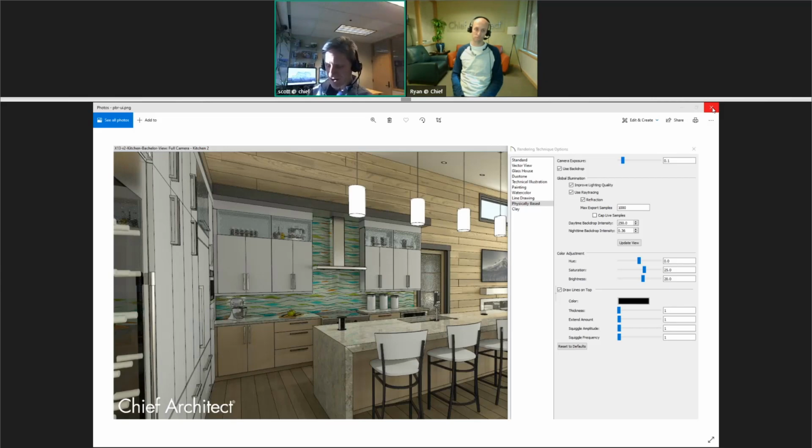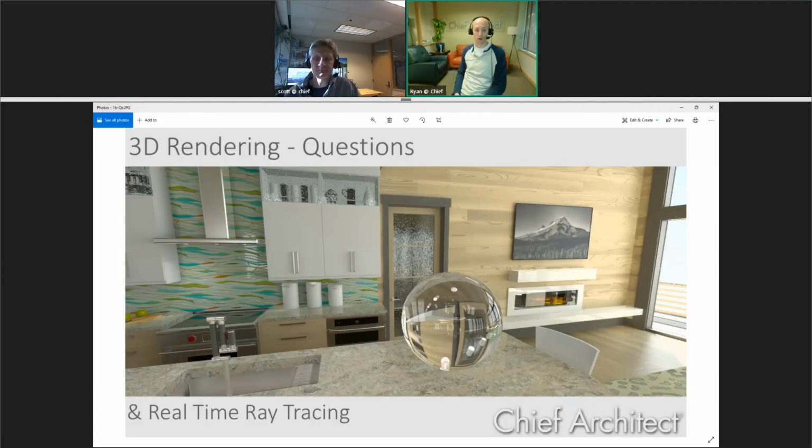Yeah. Hey, thanks for your question, Christopher. I'm going to ask Ryan to address the walkthrough question that you have. As far as recording walkthroughs, the amount of time that it takes to record a walkthrough is largely a function of how fast you can render a single frame in the program. So that's directly a function of how powerful your video card is. So it is very likely that if you switch to a more powerful video card, which the 3080 is, you will, in some cases, drastically reduce the amount of time it takes to record a walkthrough.